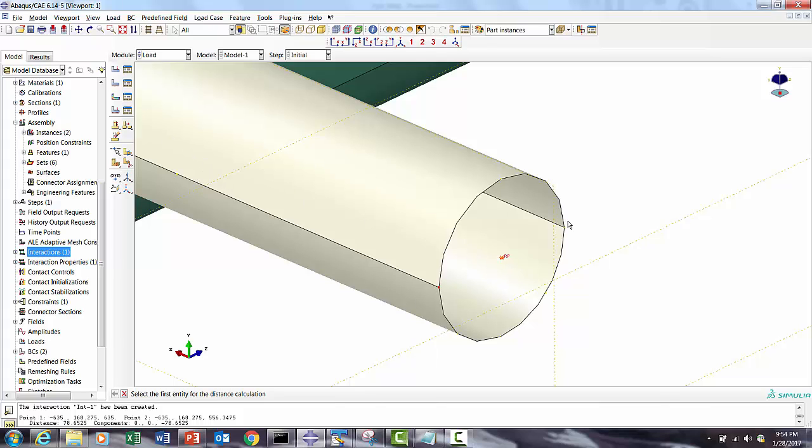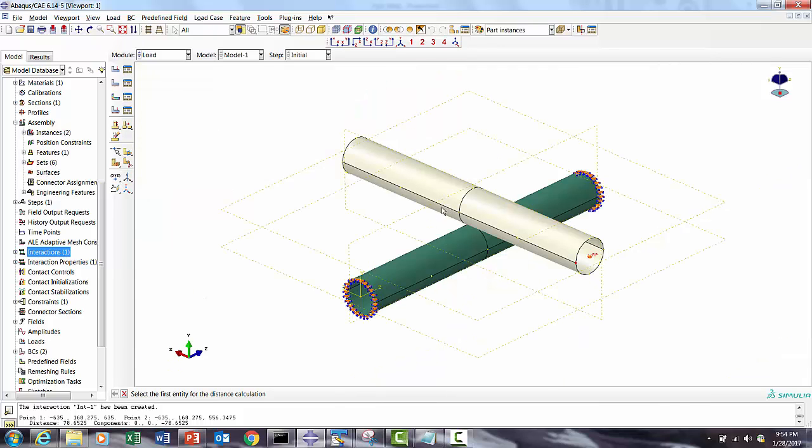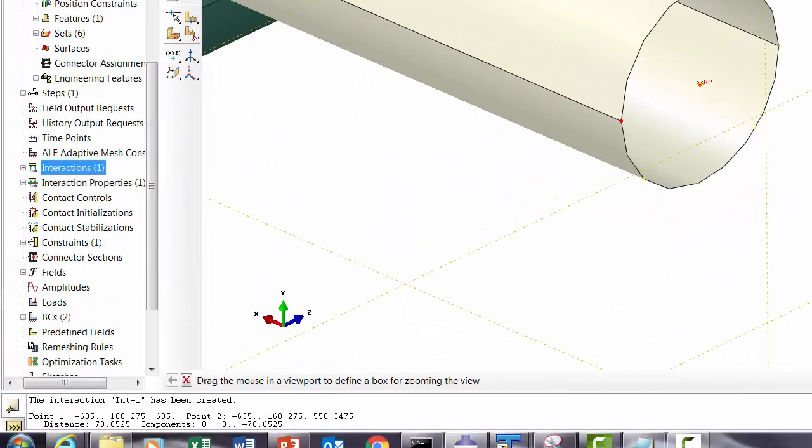How to give a rotational velocity, that is important. So first we have to get 2 points. So if I put my right hand thumb from this point to this, so thumb towards this direction, and then I rotate my finger, that will be the rotational velocity about this vector. So this is the perfect rotational velocity, so it's going to impact the bottom pipe. So I go to the prescribed one,